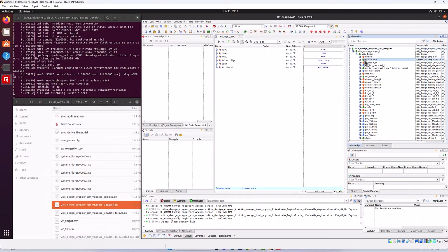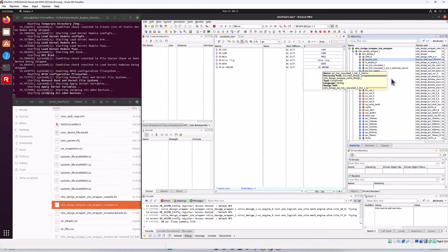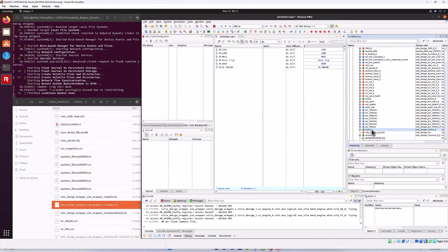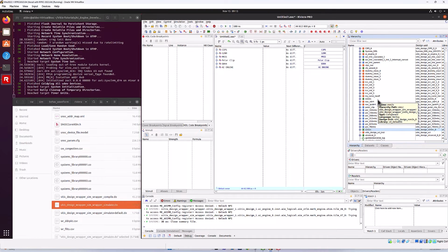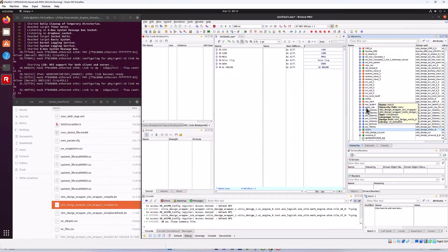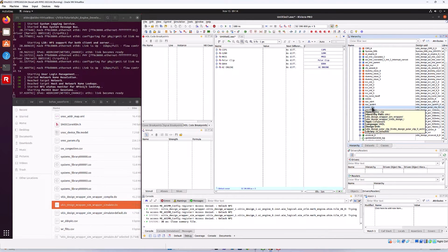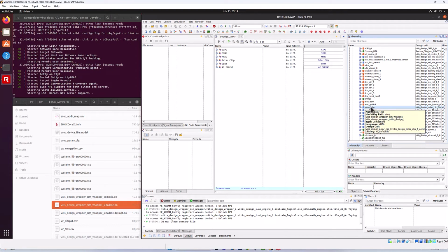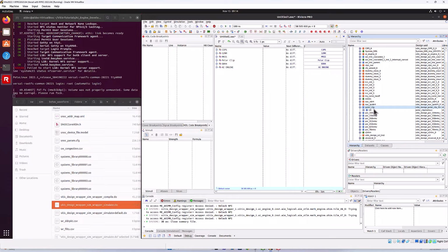Okay, the green ones are Verilog files. Okay, so systemdpa is a Verilog file. MM2S is a Verilog file, and S2MM as well. And as you remember, these are the auto-generated RTL code from the HLS flow. And the blue icons are the VHDL files. Polar Clip is the user RTL, coded in VHDL. So this is actually the user code, and we'll debug this later on.